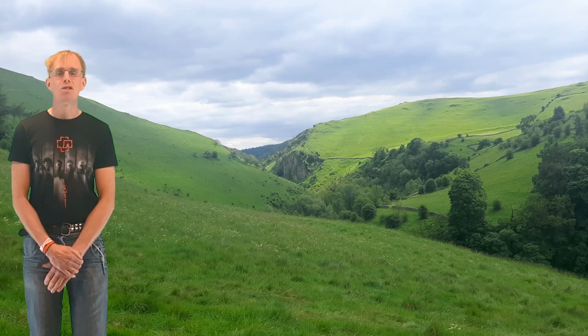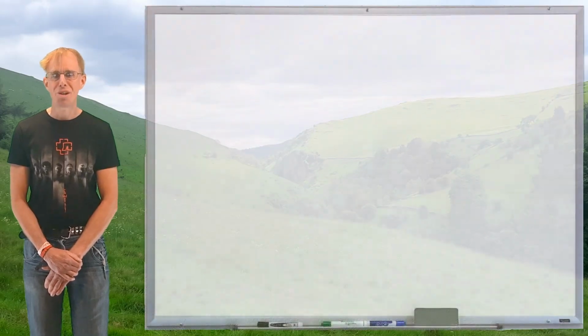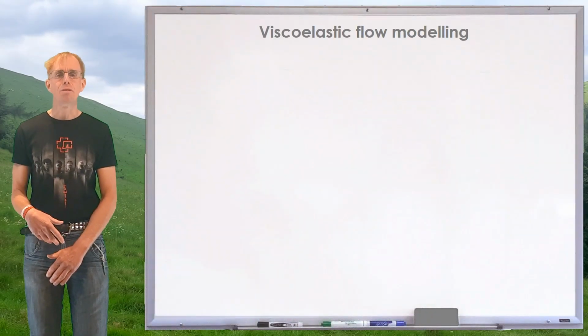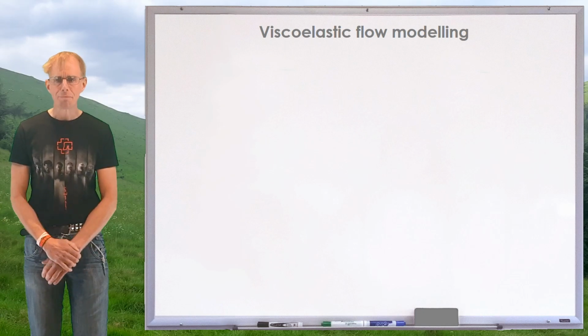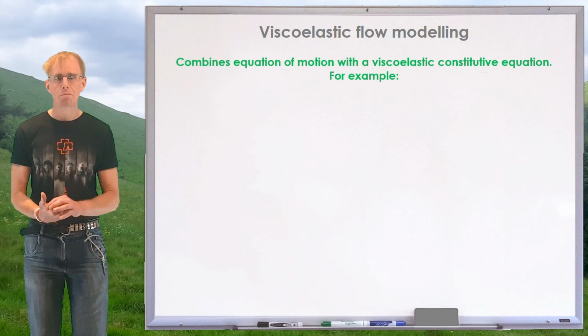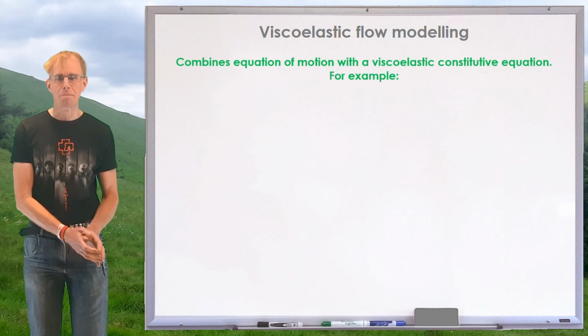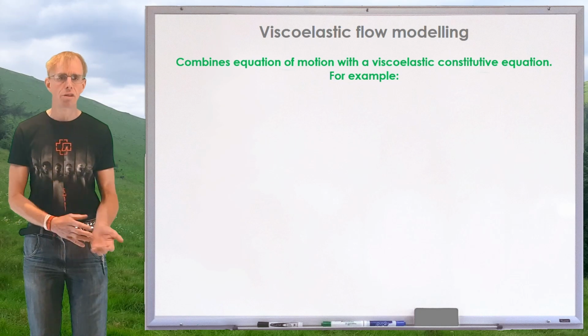Now, obtaining flow solutions for viscoelastic flow problems conceptually takes the same route, but as we'll see, arriving at a solution for a flow geometry of interest has additional and substantial levels of challenge associated with it. So let's just remind ourselves what it is that we did when we did some flow modelling before. Typically, what we need to do is to couple material response to conservation of momentum. And so that involves combining an equation of motion with a constitutive equation.